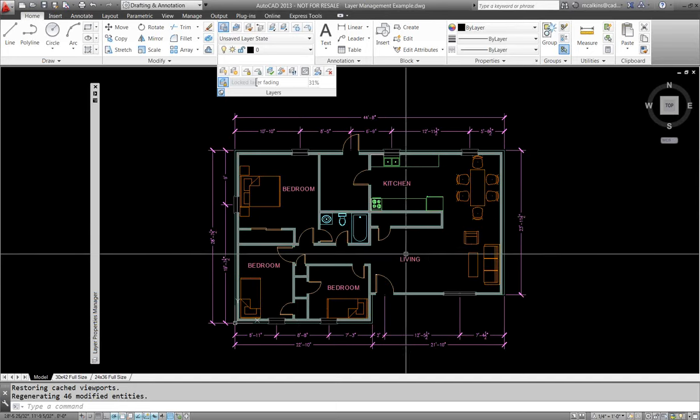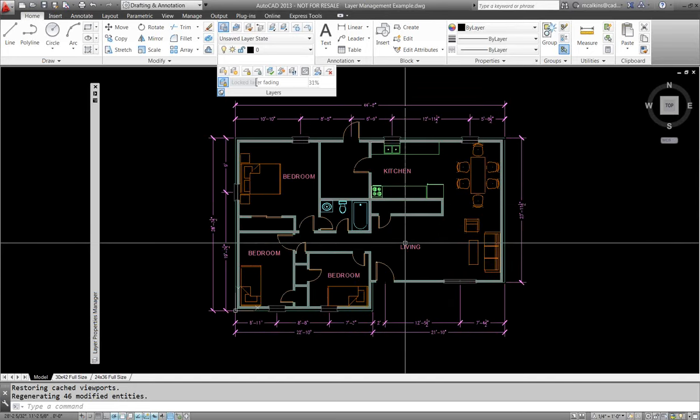Yeah, there are some implications when you get into what we refer to here as the vertical products: Civil 3D, AutoCAD Architecture, AutoCAD MEP. There are a few things that are affected, because the objects, like intelligent walls and ductwork and piping, contain layers inside of the object itself. They contain multiple layers. So there are a few more implications when we get into applying layer states there. I guess it hadn't really occurred to me what gets affected and what doesn't when you set up styles, etc.